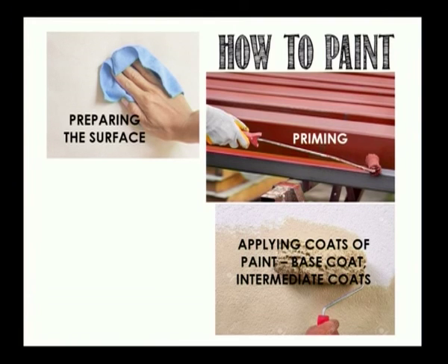The minimum required is two coats, where the first is done in one direction and the second coat is done in the opposite direction, such that the final product does not have any brush marks. Both the horizontal and the vertical brush marks merge with each other and become a plain film. If you're not satisfied with the color intensity, you can keep applying the coat again and again to get the proper color intensity.